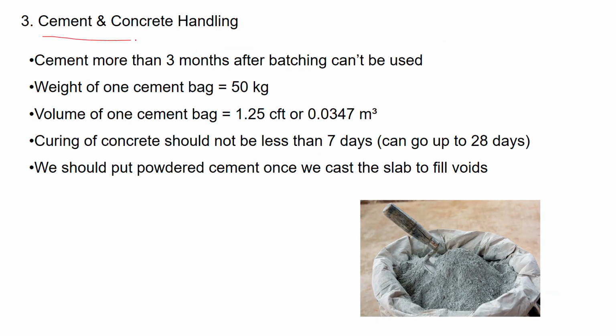Next is cement concrete handling. Cement should not be used if it is more than 3 months old. Always check the date on the cement bag, and be very careful that it doesn't cross 3 months. The weight of one cement bag is 50 kilogram. The volume of one cement bag is 1.5 CFT